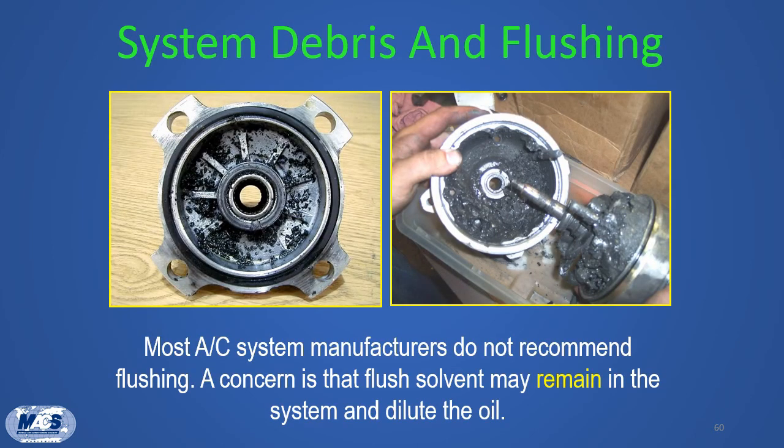Open vent flushing often will not remove debris from a system. Connecting flush equipment to the service ports, even with the valve cores removed, will not provide adequate system flushing and may not result in the removal of debris and other substances.